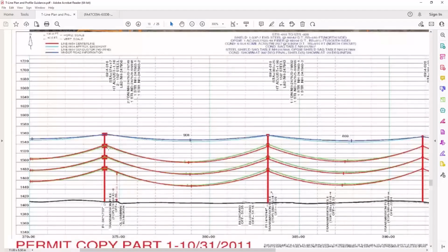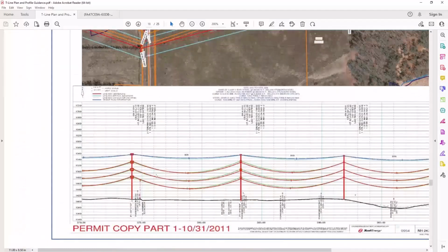So we can tell that this phase conductor has this attachment and may sag 20, 40 feet, typically illustrating the maximum sag characteristics, either due to maximum loading conditions or maximum loading conditions with some sort of physical ice loading or wind loading. So that gives us an understanding of the minimum earth to phase conductor separation, which can yield a more conservative AC interference analysis.